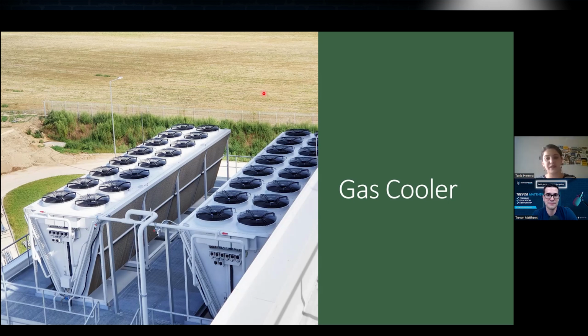The heat transfer between the refrigerant and the cooling medium in the gas coolers or condensers occurs primarily through convection, because the hot refrigerant releases heat into the cooler medium as it flows through the coils or tubes of the gas cooler or condenser. And we also have a little bit of conduction, because within the walls of the heat exchanger tubes of our coils, the heat is transferred through conduction.